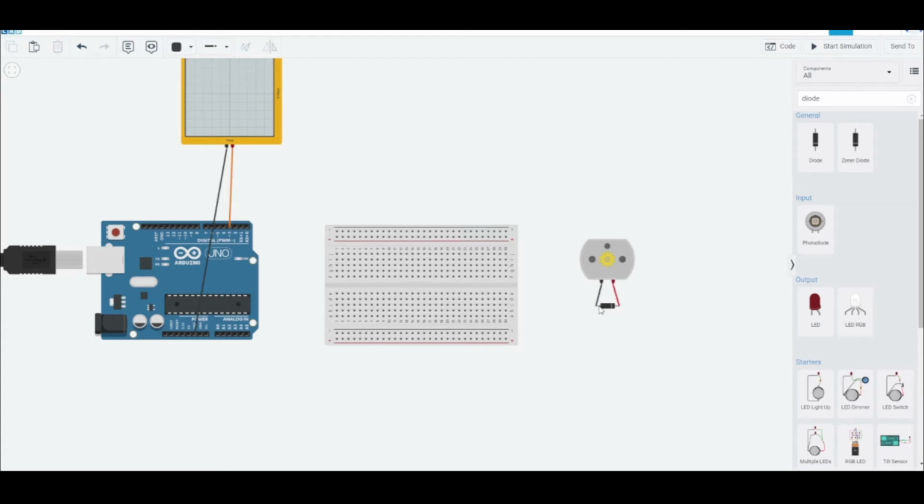And if we just shut down the motor, that current will continue through the black line and through the rest of your circuitry. But by putting this diode here, we'll actually have a little loop which the current can just go through and not damage the rest of the components that are over here.